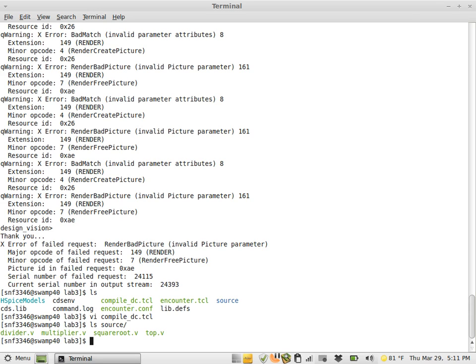But if you have a test bench, by the way, you don't synthesize your test bench. Test bench, remember, is a separate Verilog file to simulate your design. You don't take that for your synthesis. You just take the parts that make up your circuit. You don't take your test bench with you.